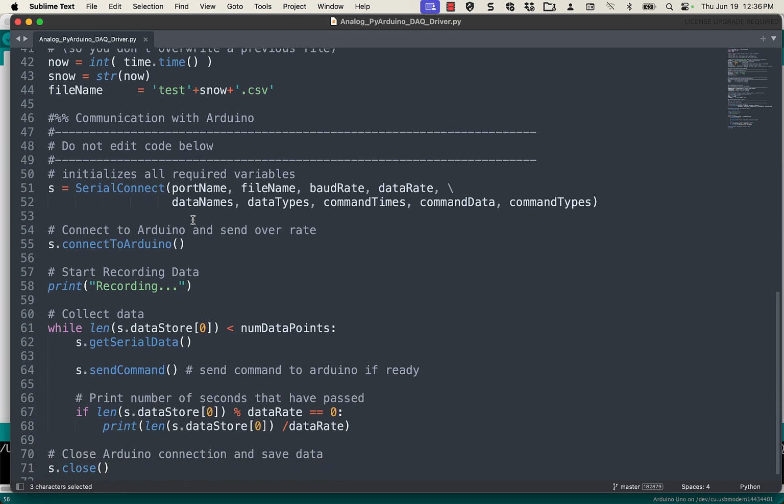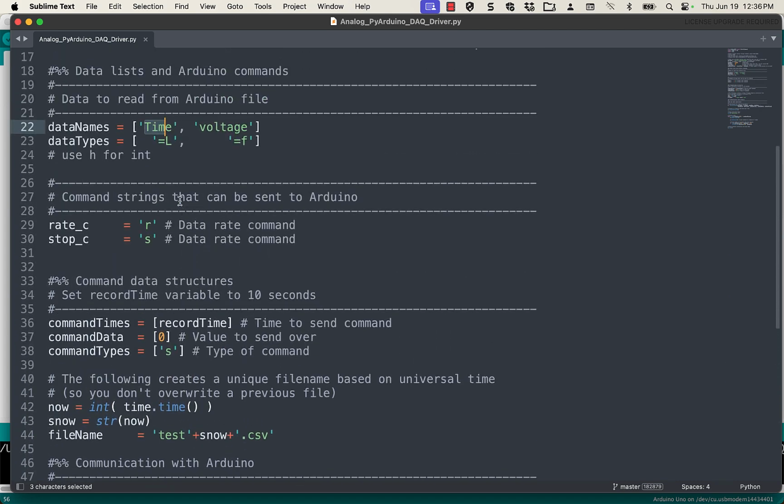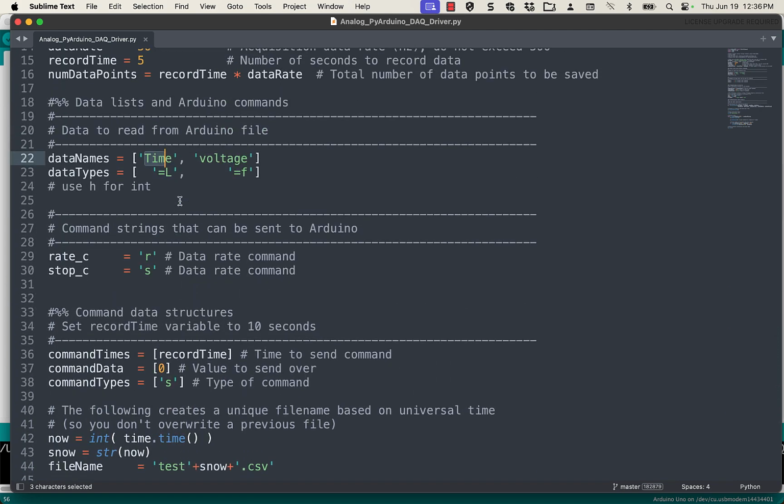The rest of this stuff, what it's going to do when you run this is it's going to start and it's going to count down. It's going to show you a countdown on the screen, and it's going to say, I'm going to start taking data. So for example, you can hold your pendulum at 90 degrees and hold it there, and you can say run, and you run this thing. It'll start running, collecting data, keep it held, and then you let it go after it starts collecting data. That way it collects that little flat region of the voltage not changing, and then it'll start collecting.